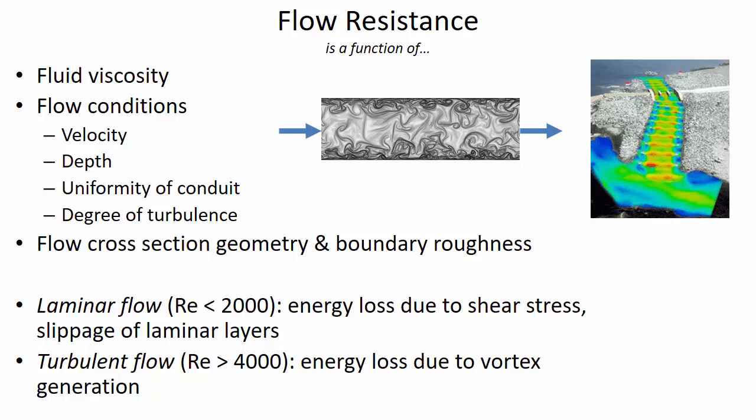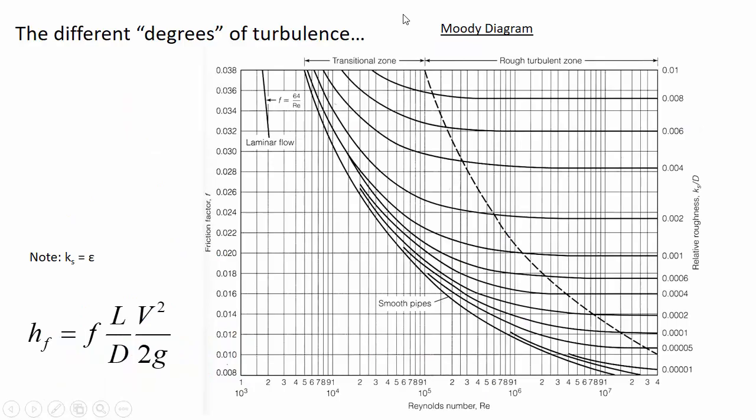So, if the flow is laminar, it's actually pretty easy to estimate flow resistance. But the flow isn't laminar very often. We had to go to some pretty extreme lengths in the lab to visualize laminar flow. We had to have that really narrow tube, and the flow was controlled with the valve. We barely had the valve open when we were injecting the dye. It's pretty uncommon to have laminar flow conditions, and so normally there's going to be turbulent flow, and that makes it more difficult to estimate the flow resistance because the water is behaving more unpredictably.